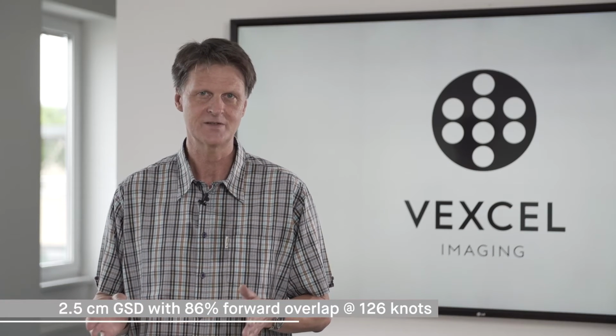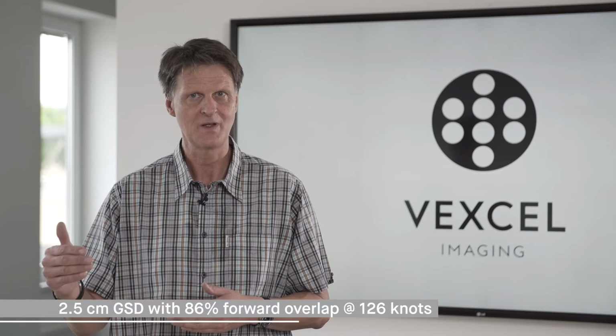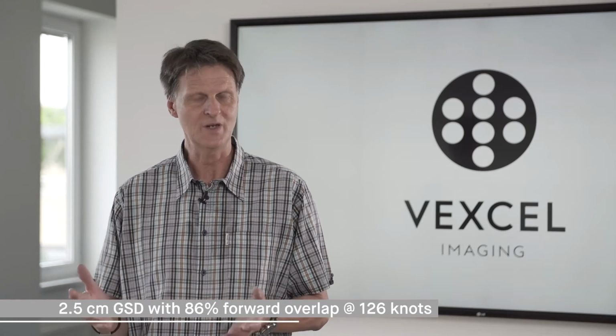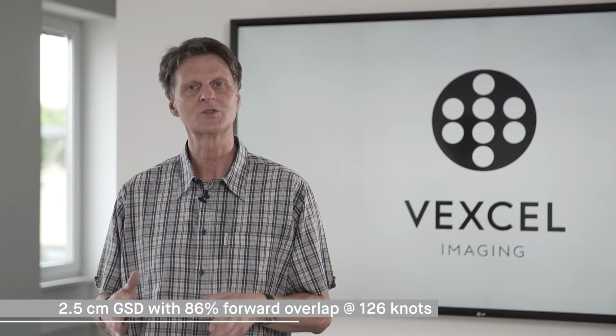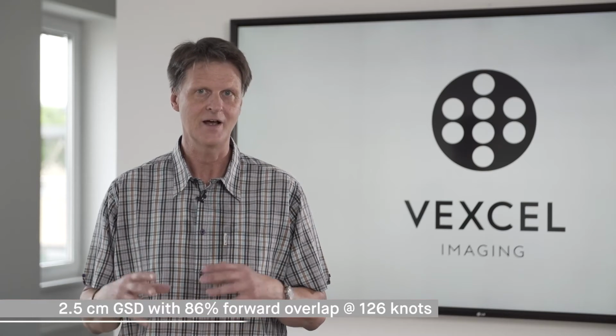Just as an example of what this means, assuming you want to fly a high resolution project, 2.5 centimeter ground sample distance, that's impressive, with 86% forward overlap. That is also impressive and ensures utmost quality in your 3D data. And you can do this with the Osprey 4.1 at 126 knots. That's an unbelievably high flight speed for such a combination of ground sample distance and forward overlap.